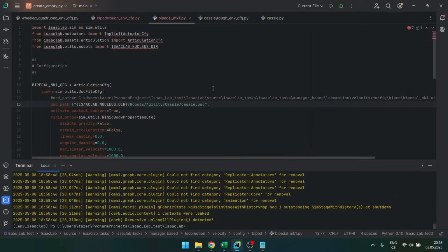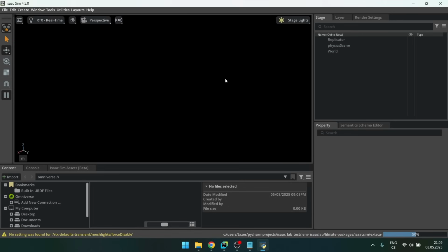You saw the 8 Cassie robots. That means that this USD file has been loaded, but if I used my USD file, it doesn't load. So the issue is either in the USD file or even further upstream in the URDF file. So what I'm gonna do is I'm gonna take a URDF file which I know works from the Robotmania YouTube channel. I'm gonna convert that into USD, try to run that, and if that doesn't work, that means I'm probably doing something wrong with the USD conversion.